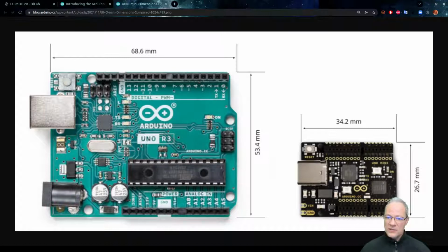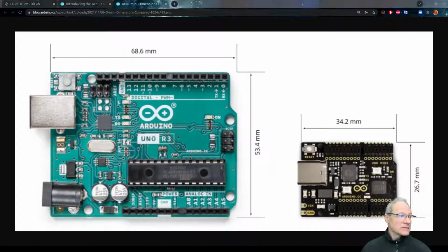And then we can have digital pins. We can attach things like switches or LEDs, or manage some more complex devices such as motor controllers. For example, we could have a little robot that is driven by this Arduino through a motor shield. So there are a number of other devices that are called shields that you can attach to Arduino through these pins. Basically, you take another board, you sort of slap it on top of this one, and that's how you can get different functionality out of this board.